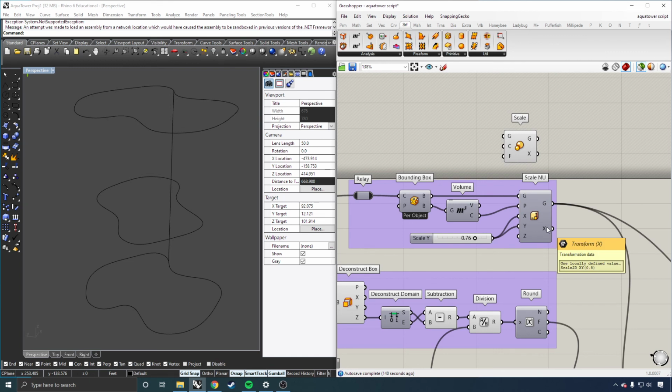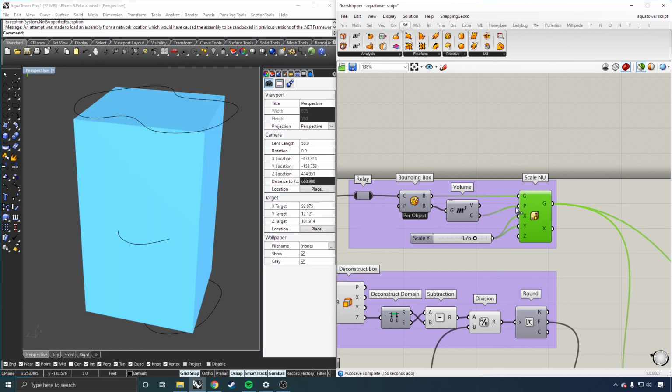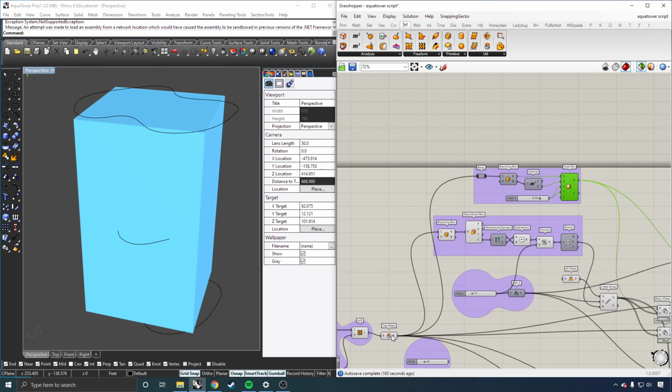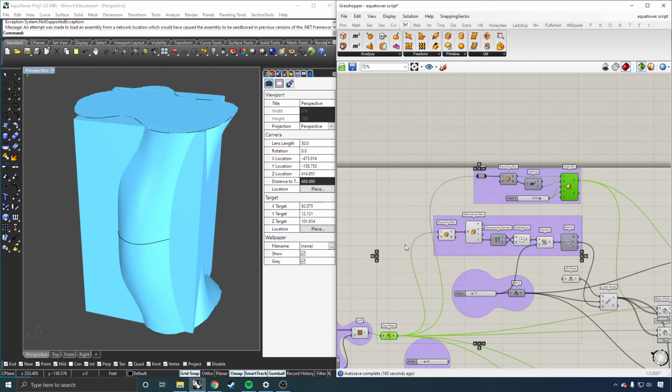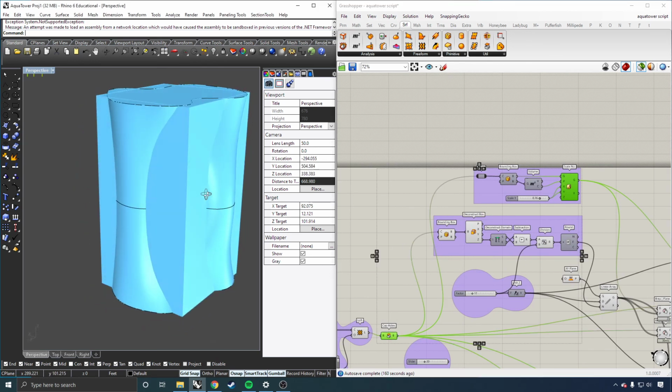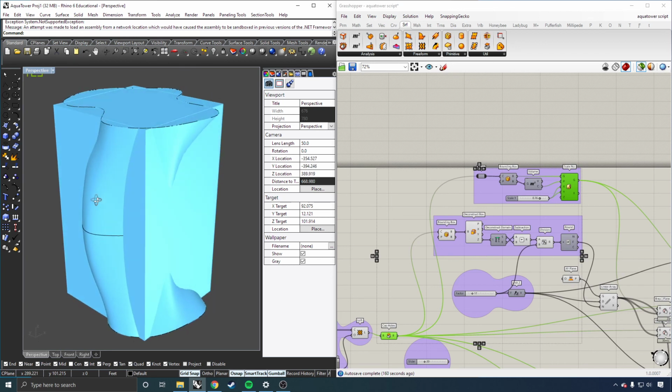In our case, it is saying Scale 2D, XY 0.8, which is essentially how you would put that in Rhino. But we do that to make sure that our bounding box is a little bit smaller than our normal object. So just by seeing these, we can see what that relationship between the balconies and the actual floor size is going to be.